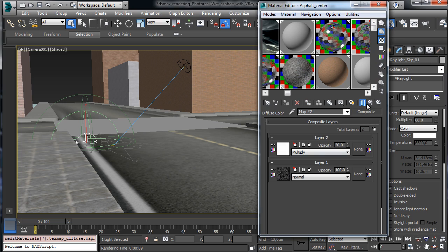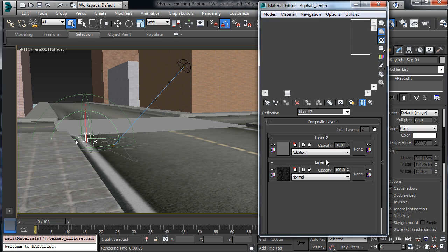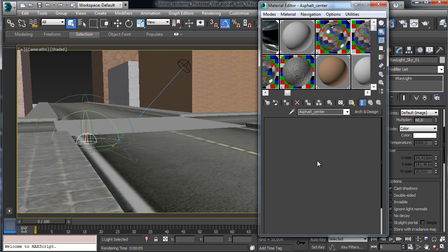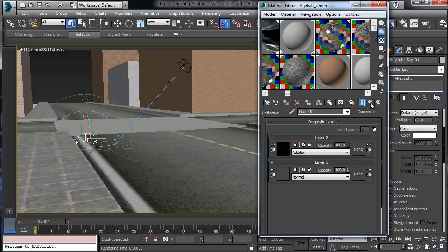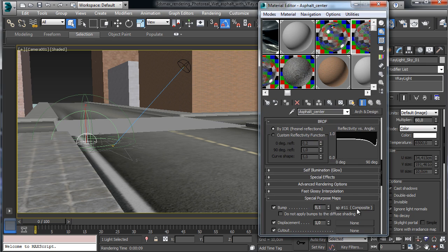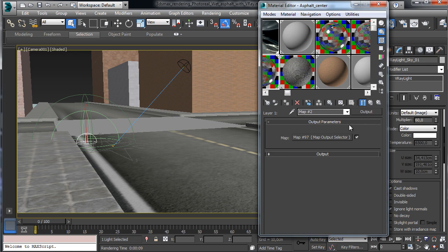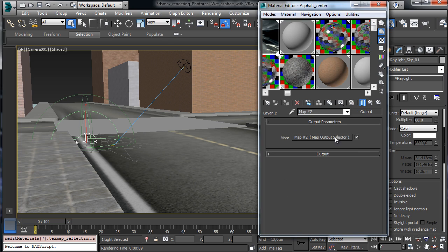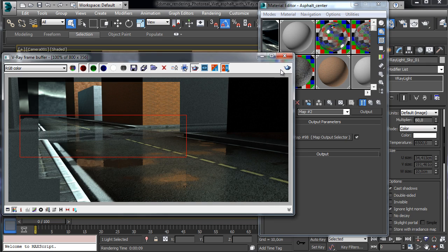and same thing can be done for the others. So let's go in the reflectivity, we copy this one, and in the reflectivity at the lower level paste. Same for the glossiness. So let's see, it's just a map, it's not a problem. And let's go to the bump and copy, and inside the bump we can paste. Okay, we can try to make a preview for the central area to see if everything is okay. Okay, obviously it is using also other maps, so it is not so precise, but it's nice, it's working.